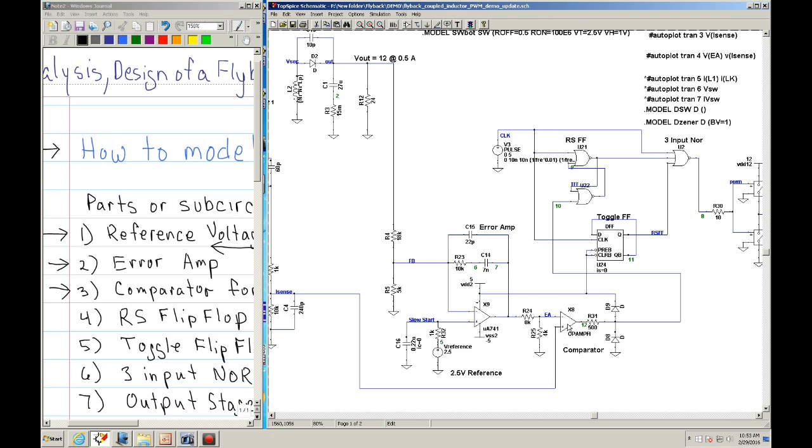What I'm using here, if you notice, doesn't have a voltage rail, because I wanted to keep the model simpler. So I'm using an ideal op-amp as a comparator. Basically this will give you infinite voltage, in both the positive and negative. To keep it from going infinite, I put a 500 ohm resistor and a diode here.